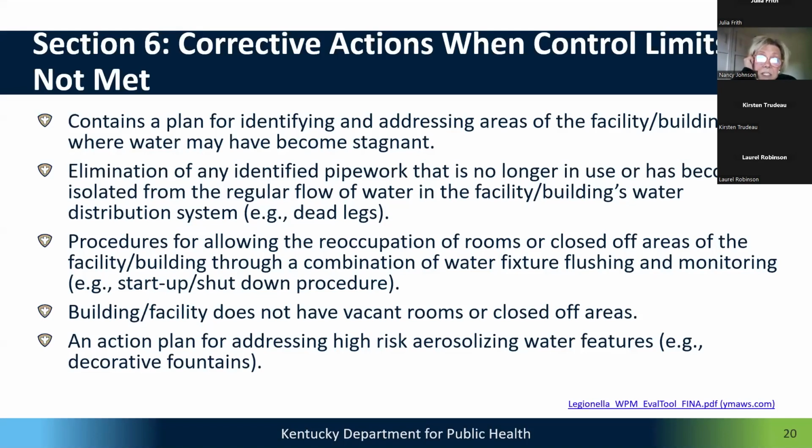So you need a startup and a shutdown procedure. And this is also part of what CMS is requiring. And your building and facility should not have vacant rooms or closed off areas. You need an action plan for any high-risk aerosolizing water feature that you have left in place. So going back to the aquarium question from last week, if it doesn't have a bubbler or an active way that aerosol is generated into the space or room around it, a still water is maybe quietly evaporating, but it's not an active aerosolization of water.